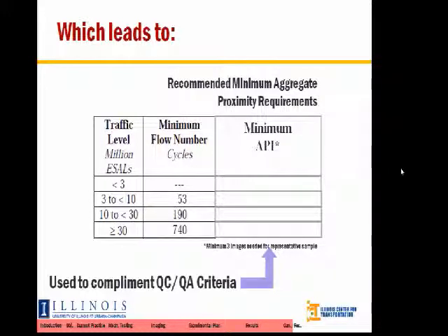Do we really care what the density is of the pavement that we're driving on? No. We're concerned with the performance of it. So if we have a means of estimating or approximating that performance, we are making an improvement. Okay? So rather than using a constant density for all HMA, this starts to allow us to slightly alter the required density. Even if density remains the easiest parameter to measure in the field, we can determine a more appropriate density for our specific pavement.